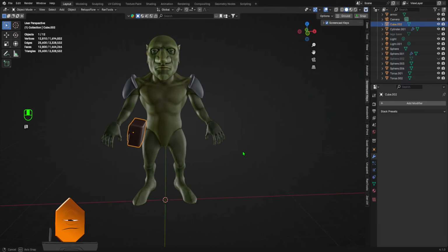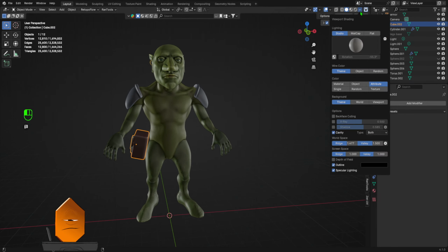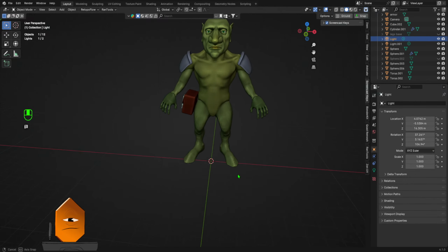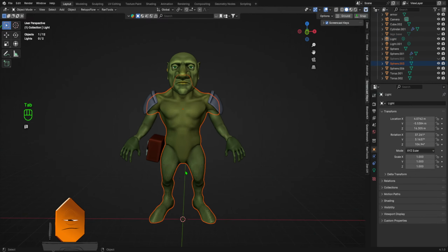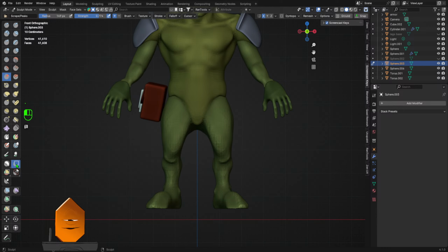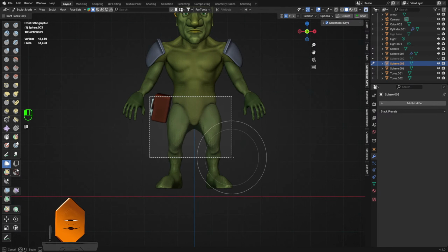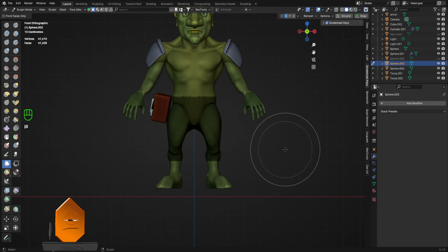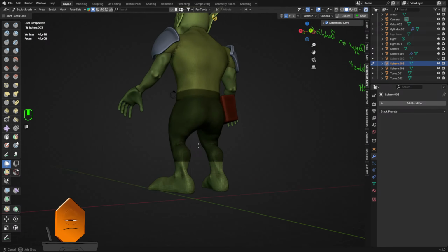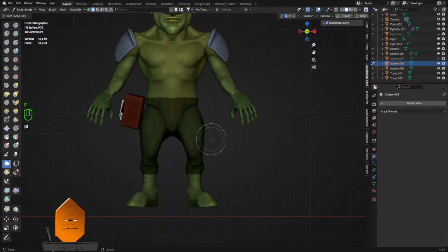Let's go to world. Themes, fine. Not kept. Okay. Select this. I'm going to go into sculpt mode. Front orthographic view. I'm going to box mask. If I can find it. Box mask. There we go. I'm going to box mask to probably there. Okay. Box mask luckily goes all the way through. I'm going to hit Q to do mask extract. You can find this in mask extract.